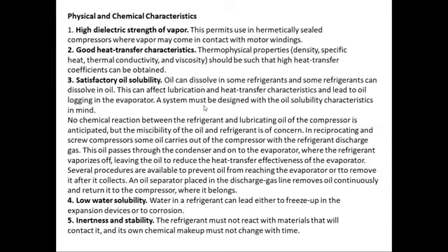If the compressor is new, probably not much, but as the compressor gets older and the piston ring gets weaker and weaker, some of the oil will escape and go into the refrigerating circuit with the refrigerant. If the refrigerant and the lubricating oil are not soluble in each other, then the oil which has escaped will never come back to the compressor.